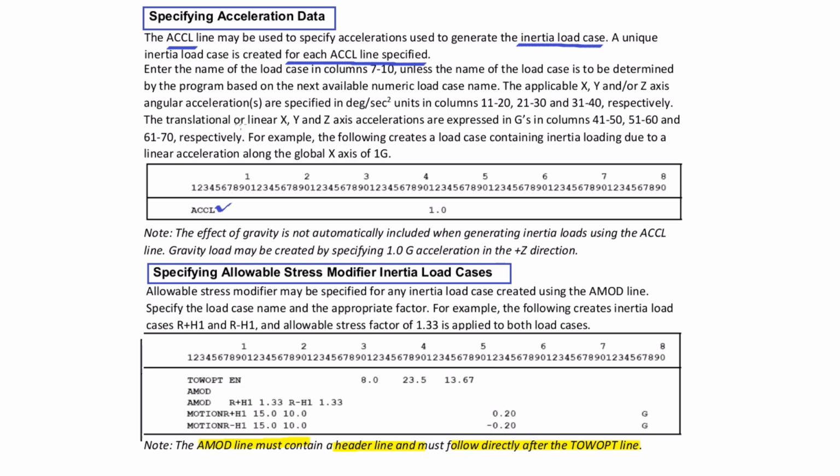It will be generated. Enter the name of the load case in columns 7 to 10 unless the name of the load case is to be determined by the program based on the next available numeric load case. That means if you don't specify, it will generate the next available numeric load case name.